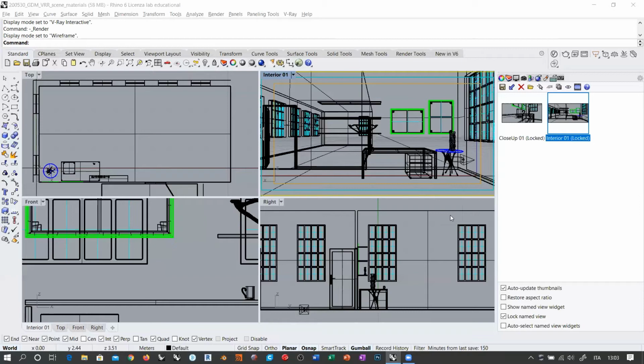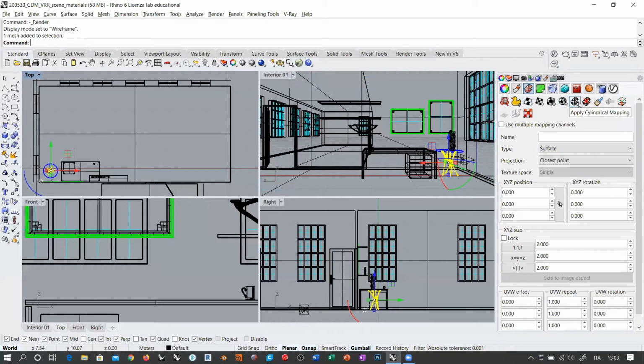What I was saying is that if you have an organic shape like this one and you want to use one of the automatic texture mappings that you have here, the more suitable is probably the sphere, because the sphere is the only geometry among cylinder, cube, and planar that is capable of orienting in any direction in space, right? So this is the problem. Yeah, the sphere is actually the only option that you have among the default texture mapping objects.